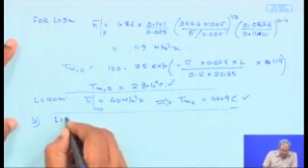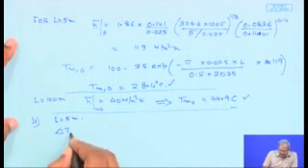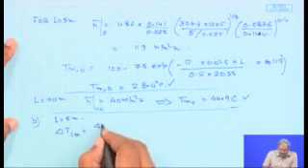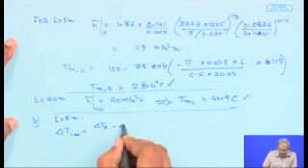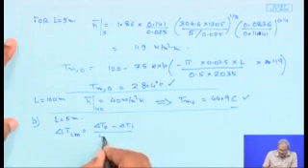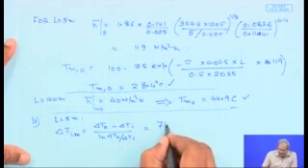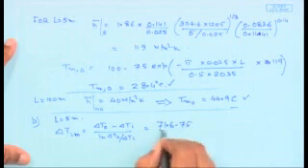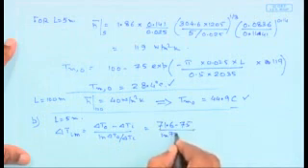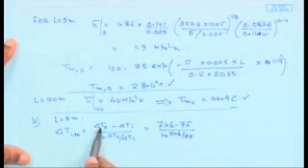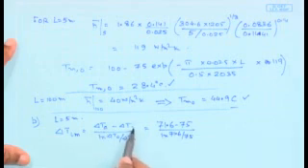So for L equals 5 meters, you calculate delta T log mean to be delta T at the outlet minus delta T at the inlet by ln of delta T 0 by delta T i. So which turns out to be 71.6 minus 75 divided by ln 71.6 by 75. So these are the values of the temperature difference at the outlet between the bulk and the wall, and the temperature difference at the inlet between the bulk and the tube surface temperature.